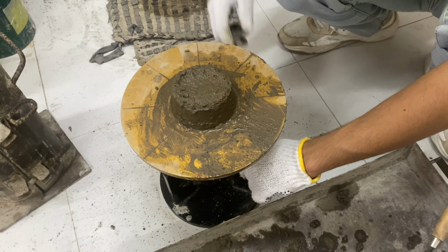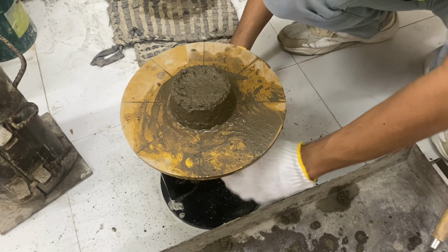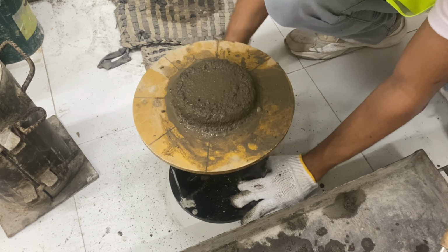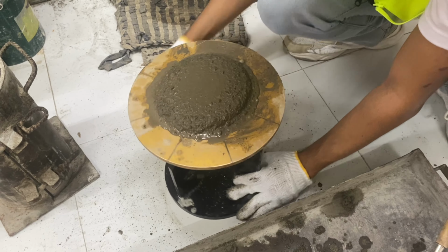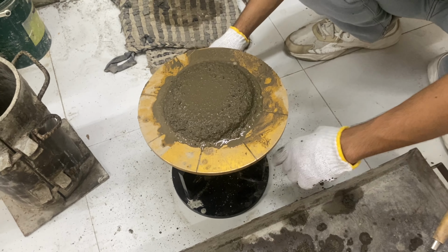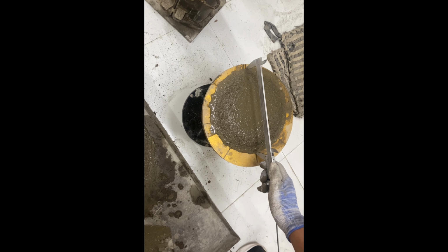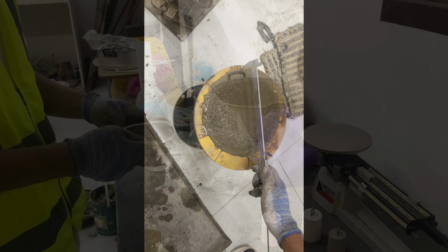Lift the mold away from the mortar 1 minute after completing the mixing operation. Immediately drop the table 10 times in accordance with specification C230 or C230M. Measure the flow by determining the resulting increase in average diameter of the mortar mass using calipers.